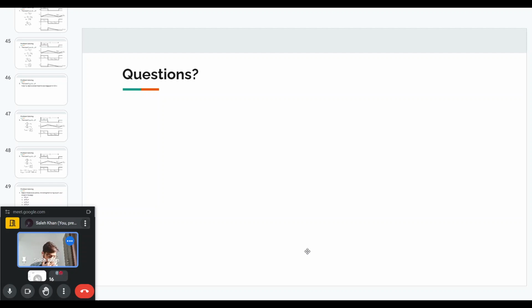the simplest way. First have a boost PFC, which is a rectifier and then a boost converter, and then it will produce a DC voltage, and then you can have an inverter. But again, it is single phase power, which is not constant power. It has second harmonic fluctuations, and the three phase power is a constant power. So you will need a large DC bus between the boost converter and the three phase inverter.